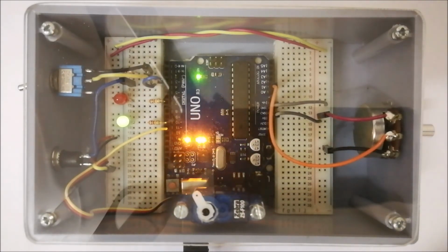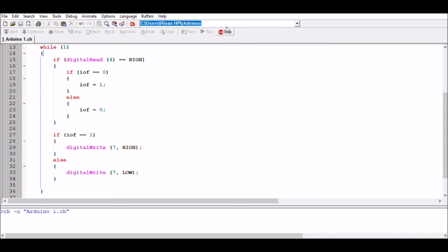So you want to prevent using delays and rather use external interrupts and have the code keep on running and checking those external interrupts, than having external circuitry like different resistor values to do that discharging of the button and having any delays in your actual code. Then we can stop the code over there.